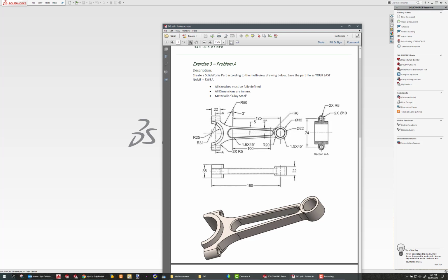upon this center line. So theoretically, if I model the top half, I could then mirror it down to get the bottom half, and then my model would be complete. I'm going to keep that in mind as I model this. And then the other thing that you should recognize is this is an extrude problem, and the part's going to be created using the boss extrude base function in SolidWorks.